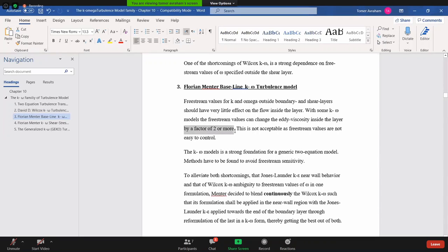Still unresolved because of the problem of transferring, especially transferring from RANS to large eddy simulation. I mean, you don't have any turbulent content. You model all the turbulence, and then suddenly you need to have some turbulent content inside the large eddy simulation zone. One way to overcome this is using the scale adaptive simulation model.